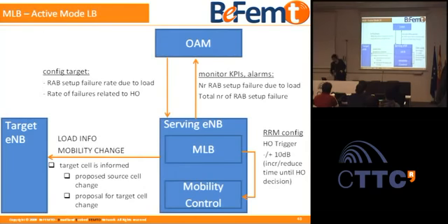essentially your users, and this is what happens. You have a serving eNode B, you have a target eNode B, you have your operating center, which is telling you how well you should perform. It's your manager, who tells you, you have to have this target at the end of the month. And that is a decision taken here, really. And you can essentially tweak the handover parameters. You can say, okay, I'm going to hand over somebody if the SINR is maybe 10 dB worse or better than what I had said before. So you can load people forth and back. That's quite an interesting option for the load balancing.